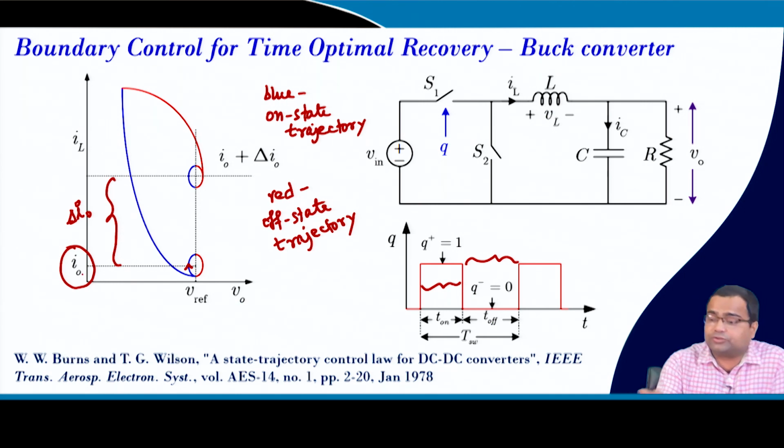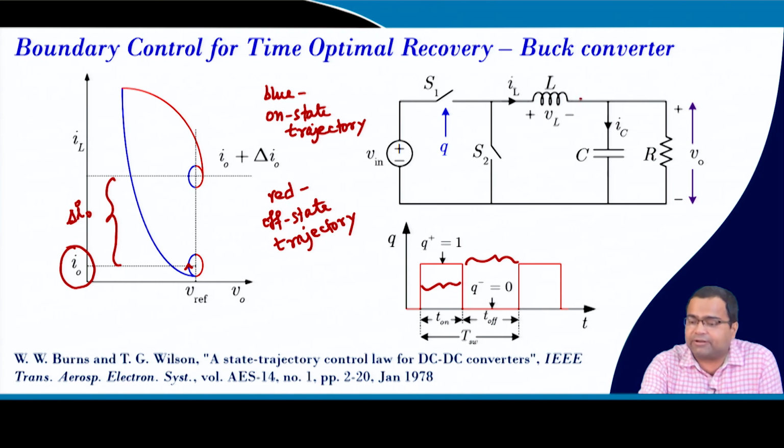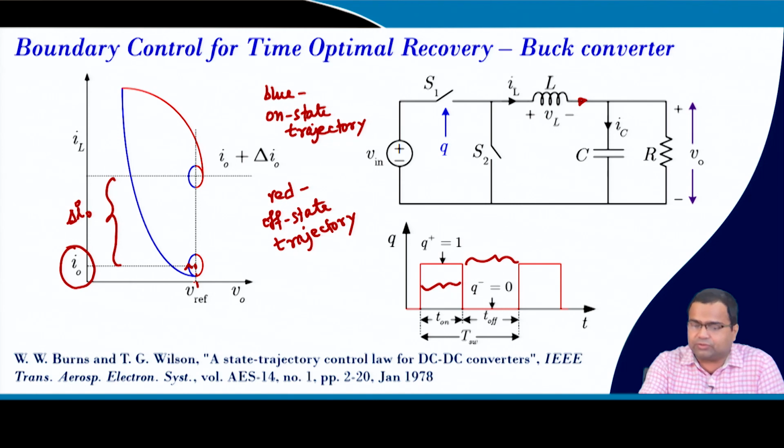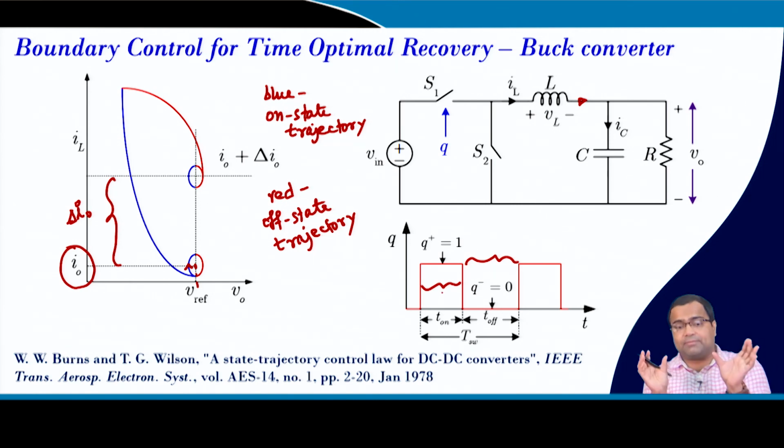Because we know for a buck converter, because we are talking about synchronous buck, the average inductor current is nothing but the load current. So, for a given load demand, we need to ensure that the average value is Vref, that is my desired reference voltage. So, we need to set a set of on off times which ensure the voltage regulation at Vref in the average sense, which should achieve a certain desired time period.